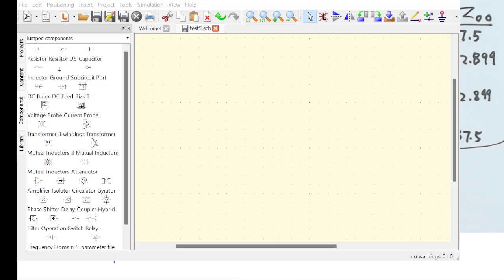The methodology that we are going to use is lateral coupled transmission line. The filter type is Butterworth. Right? You can choose other types as well, but for this question, we use Butterworth. The frequency 3 gigahertz as a lower corner frequency, 3.5 gigahertz as a upper corner frequency.